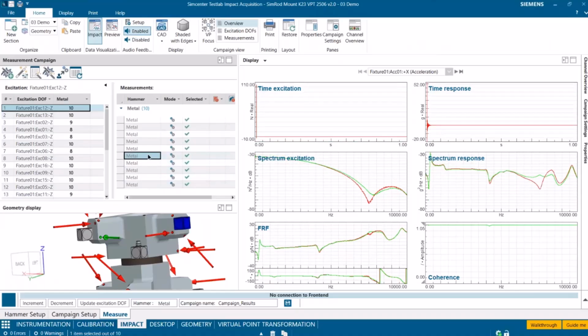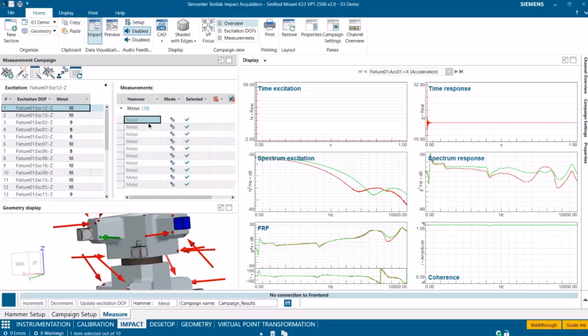Something that I really want to highlight here, because again, it makes a big difference on the frequency range and the validity of the results, is a question that everyone struggles with in impact testing, which is: when can I stop impacting the structure? When do I have enough impacts to have good data quality in the frequency range of interest? Mostly, we're using rules of thumb, like at least 5, maybe up to 10, and you should have enough good data in that data set. But in reality, you might be just having a bad day, or you might be getting tired, and maybe 10 isn't enough. Maybe you actually need 20, or maybe you did a really good job and you can already stop at 5 impacts. You don't have to do the 5 extra to get up to 10.